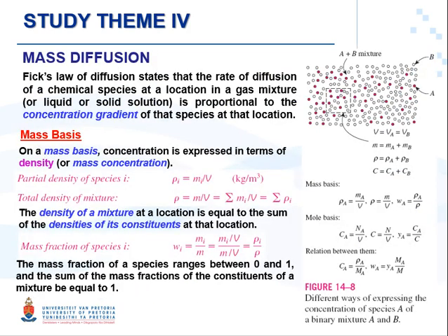Okay, now we are going to talk about mass diffusion. We just talked a little bit about mass diffusion and Fick's law of diffusion, but here we are going to speak about different ways of showing concentration, basically different languages. The concentration of a species can be expressed in two different ways: mass base or mole base.